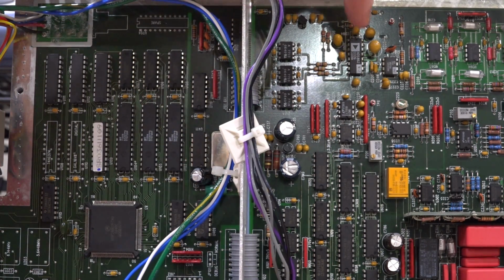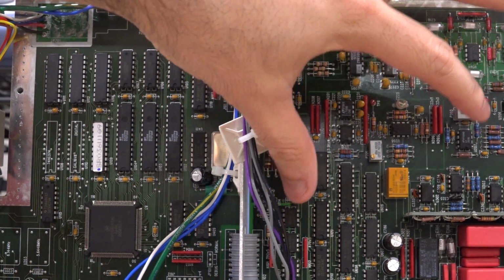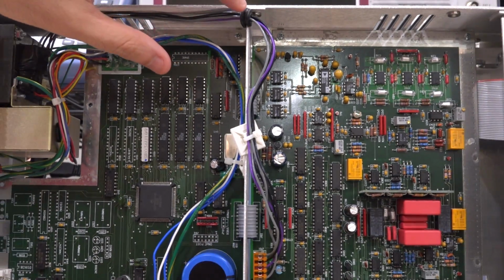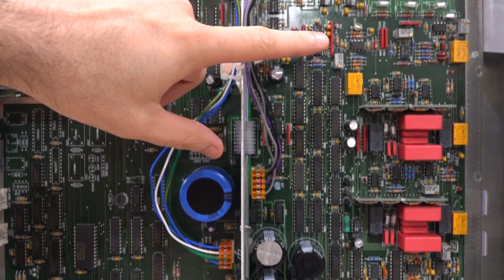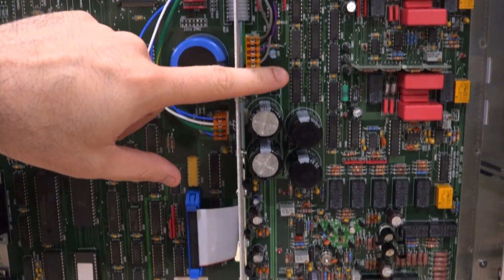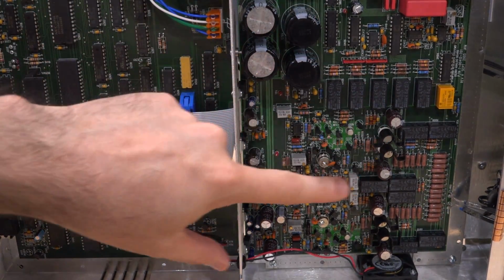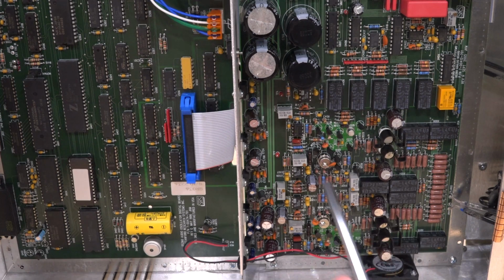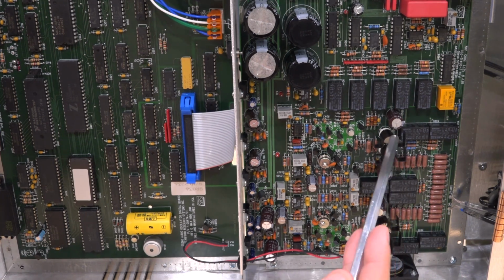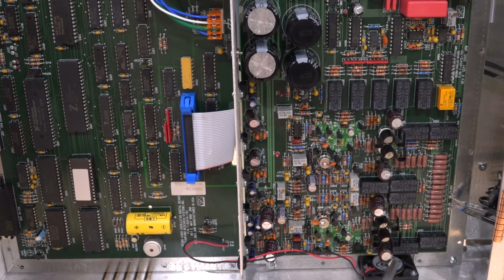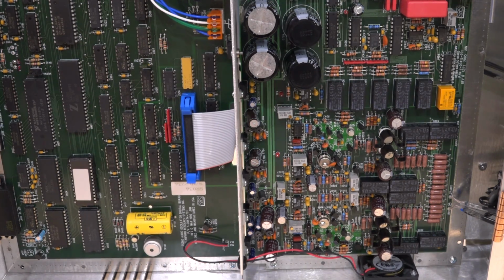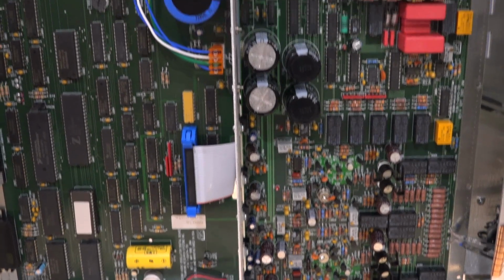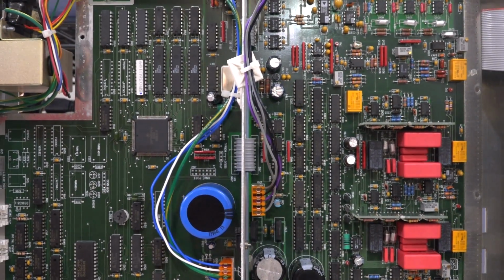And after that, what comes out goes through this entire section, and all the functions that I showed you: the anti-aliasing filter, finer output adjustments, and here all the relays that I was talking about. Look how many relays there are here and how many components can be switched in and out. Here are our main output amplifiers, the two discrete components, and they have some heatsink on them with a fan at the bottom which blows over them. So this is the only part where we have high thermal dissipation there. Yeah, looks really nice.